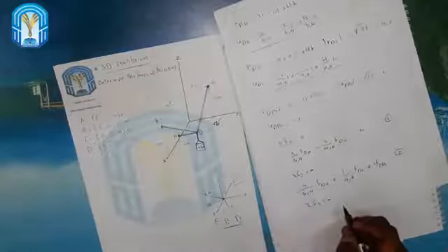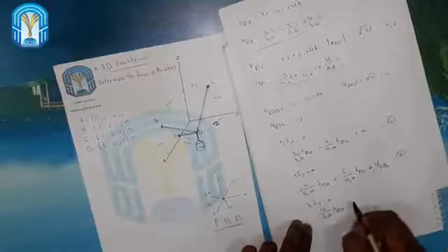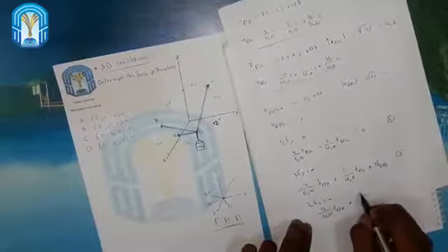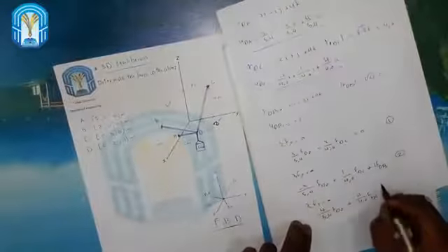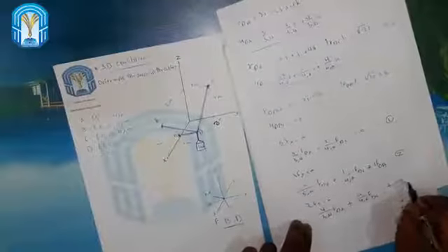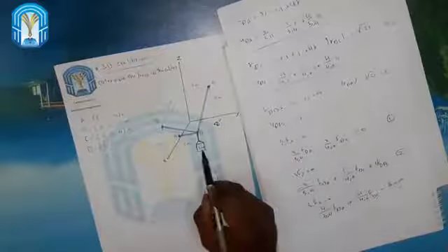And summation of z equals 0: 4 over 5.4 FDA plus 4 over 4.6 FDC minus 1550 Newton for this weight. And from equations 1, 2 and 3 we will find the forces.